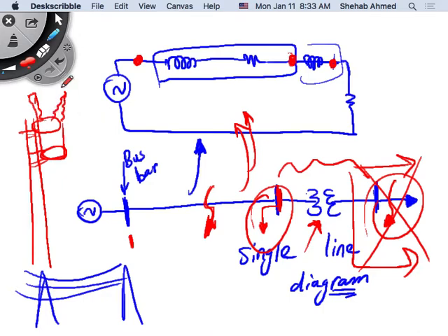These are insulators, the electrically insulating bushings of the transformer. So you would have terminals coming in, and you would have smaller terminals coming out. You have some smaller ones and some bigger ones. The bigger ones are probably where the high voltage is coming in. The smaller ones are where the low voltage is coming out.